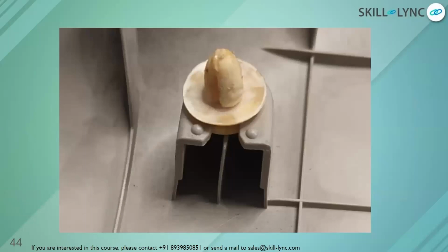So here you can see the doghouse with a push pin or a push clip. These are components which are used for temporary joints with respect to your plastic components. This will be the part used for assembling the whole plastic assembly component of your door panel, for example, to be joined with the sheet metal part of your car. Why a temporary joint is required is basically that you need to perform operations. If you see your plastic door panel, you can see lots of wiring systems available. For example, you'll have the window winding motor, the stereo system, the other switches, etc.